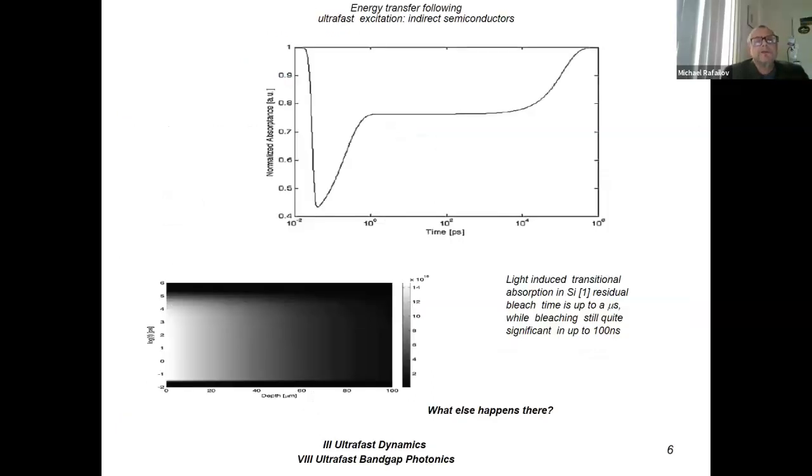So here is a picture. What happens upon the relaxation? When they eventually slide down to the bottom of the conduction band, they start relaxing, and they relax pretty fast. As we know, it's inside the picosecond time frame.